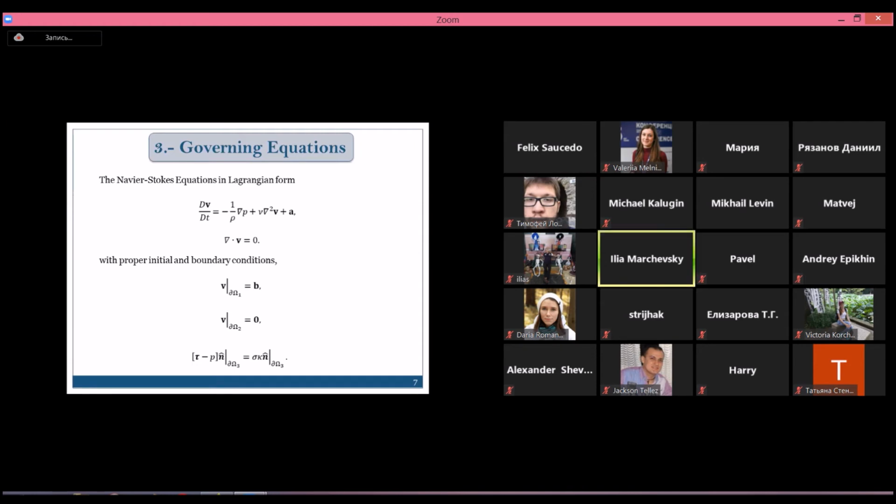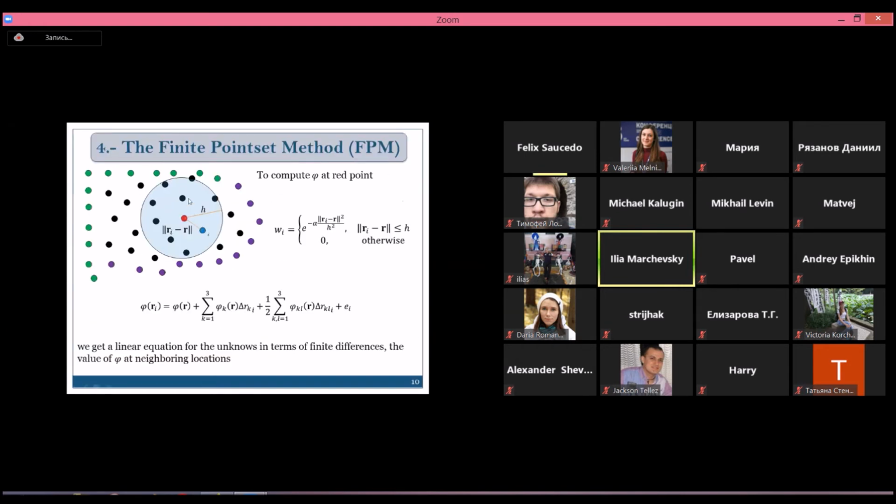And what about, for example, simulation of some liquid, just water with free surface, for example, with waves on the free surface and so on? When there is a free boundary, how can we apply the expansions you have shown on some previous, or maybe in the next slide? I mean, how to introduce the neighboring zone, this closer zone, because only, for example, half of this zone will be in the liquid region and the other part will be in some other region. If we just imagine the diameter of this zone, below it will be water, and above it will be air.